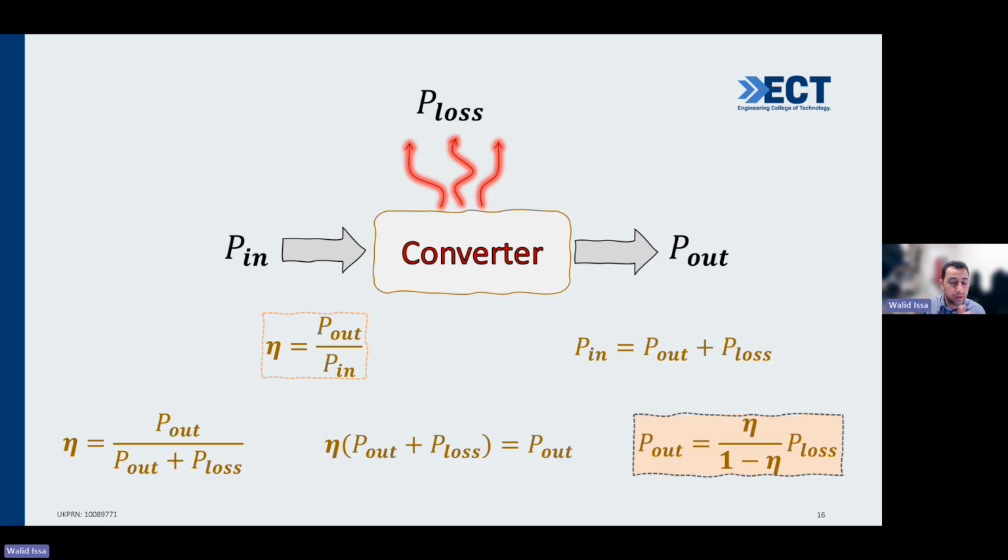Why is it hot? Because it has power input and it spits out power output to your laptop to charge the battery. But through this conversion, there are some resistors, power converters and MOSFETs, and all of them dissipate power. How do they dissipate power, or losses? As heat. So the heat is a sign of power losses. That power loss will be emitted whatever you do. You don't have an ideal system with 100% efficiency. You might have 90% efficiency, which means 10% will be losses.